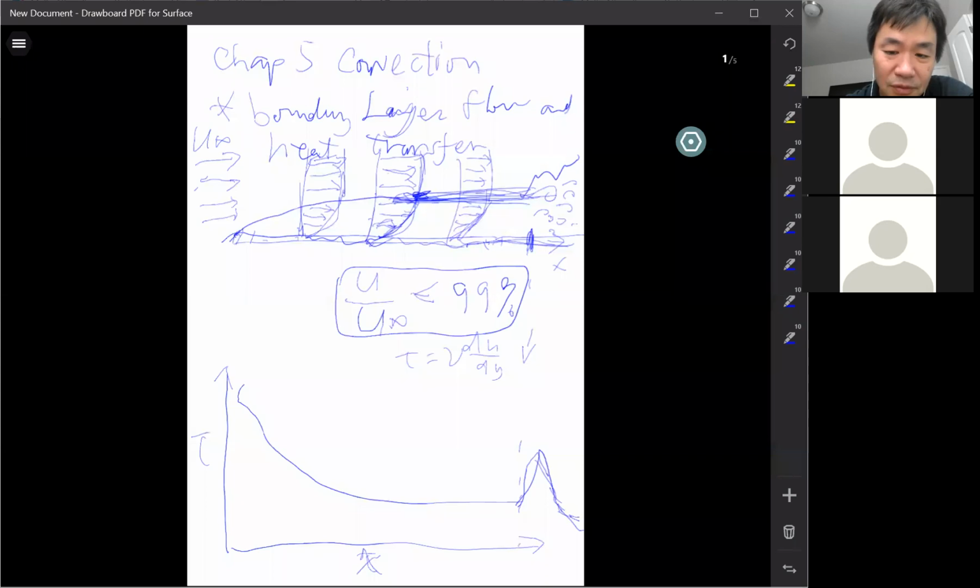Okay, so that's the behavior of the shear stress and the flow along a flat surface, with flow passing it. So now I think obviously you know how long that would be the point. I need to know, because when I design some heat transfer surfaces, I need to know where the flow starts getting turbulent. Because sometimes turbulent is good.